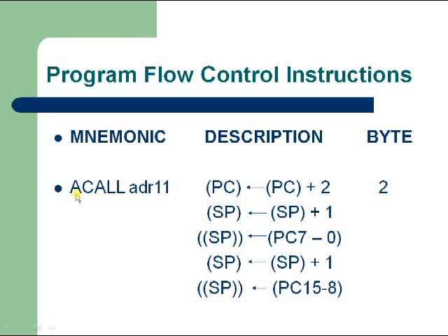Okay, so as we have called a subroutine from the main function or from the main program, control will be transferred to the subroutine. Before the transfer, the program counter value will be stored inside the stack, and this storage inside the stack is called the return address. We are storing the return address.